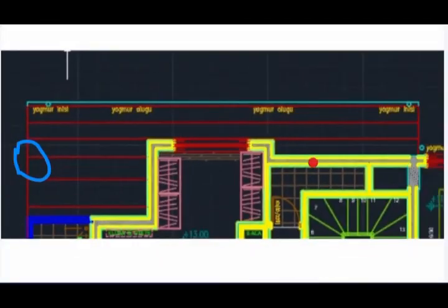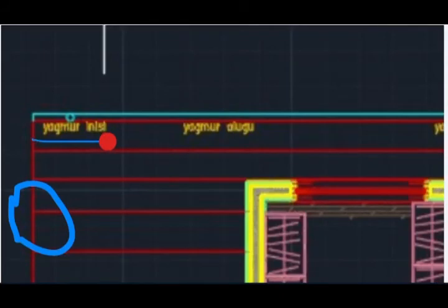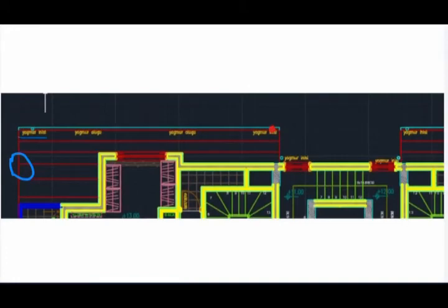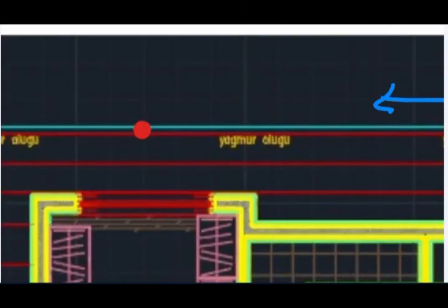And look at this information. Gutter. A gutter should not necessarily be at the corner. Maybe go 1 meter in and put one here and one in the corner. Most of you are putting it like that; they are putting one at the center. That is why, in order to have 5 meter from both sides, you can cover 10 meter. And do you know what is the reason that they didn't put a gutter here?